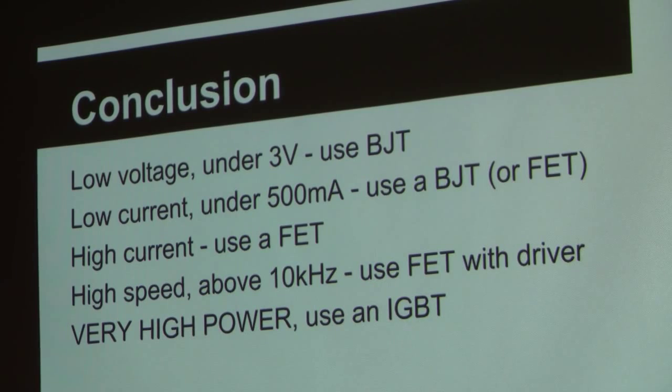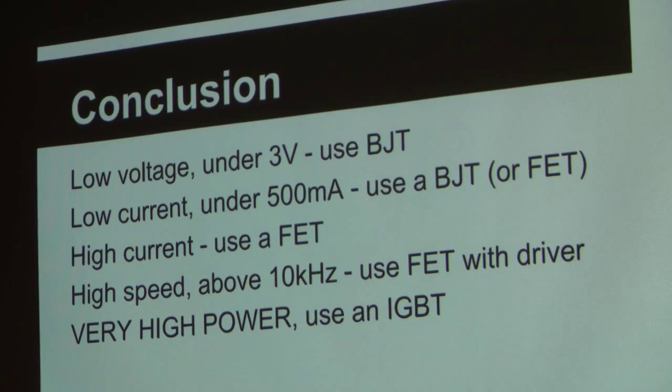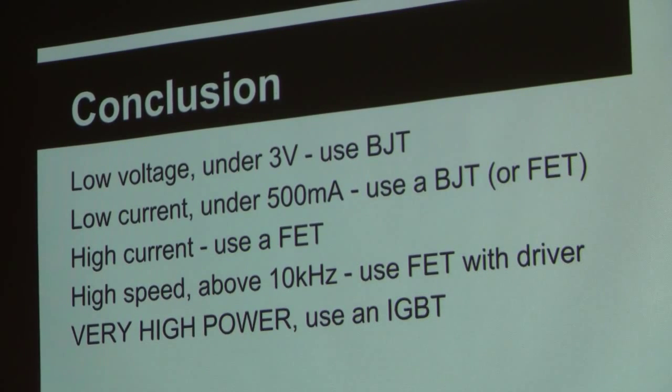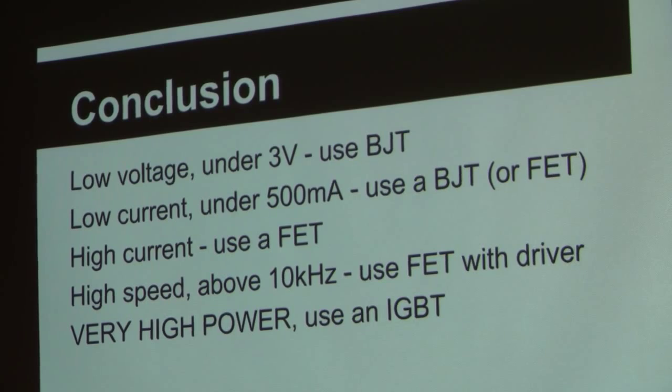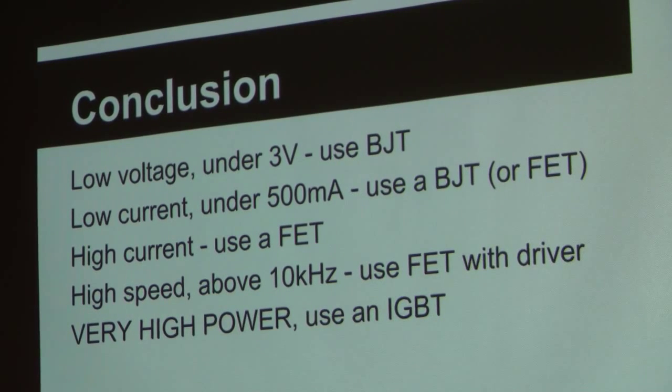But getting an output pin to push the current in and out of the gate of a MOSFET by itself, you start getting sloppy, and then your power dissipation goes up in the MOSFET because you're spending a lot of time in the transition region instead of the conduction region. But a driver will take those rise times and put them in a sub-microsecond range, so that all of your dissipation is in your conduction region for the MOSFETs just itself.